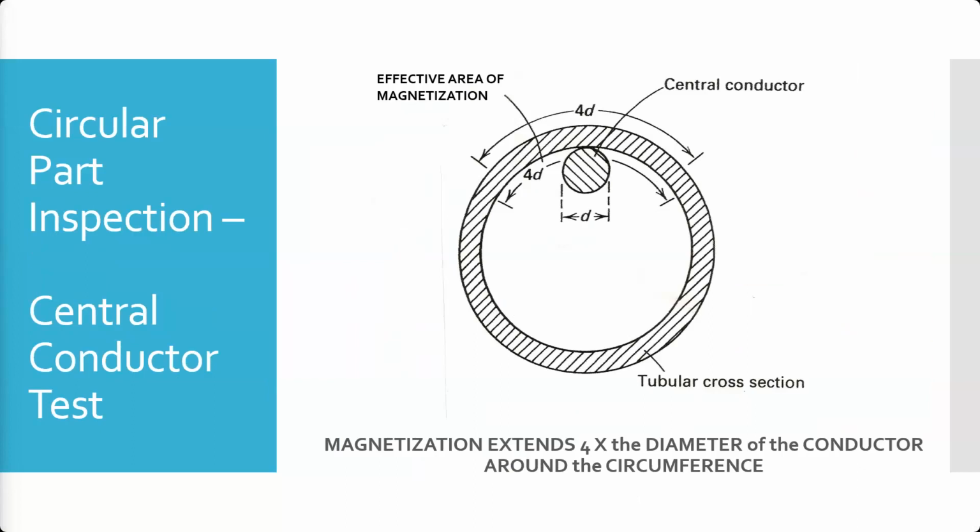We can't directly measure a circumference most of the time unless you have a piece of string and a ruler. Whereas we normally have calipers that we can use to find the large diameter. So let's say the diameter of our tube, usually written as large D, is the outside diameter. So from the outside to the outside, the OD of the part equals 3 inches.